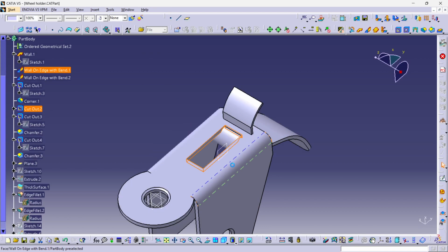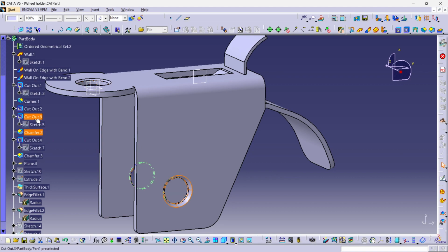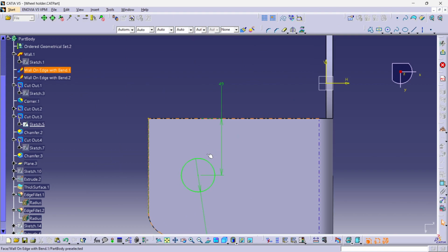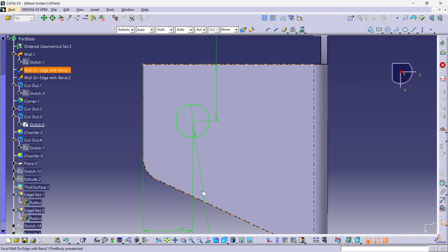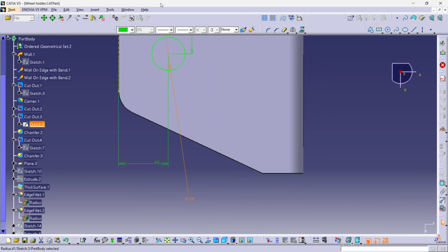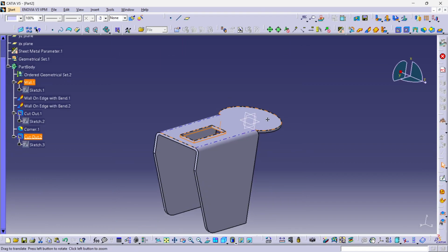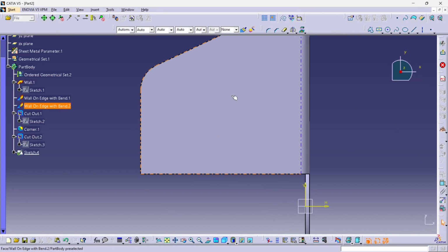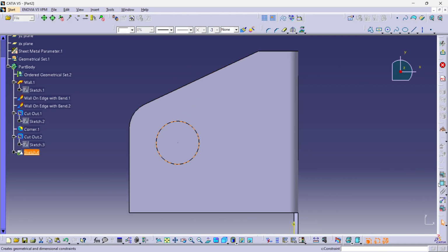And going back here, now let's go for this holes. Okay. This is 49 from this side, 43 from this side, and the diameter is 29. So just select this plane, the middle plane, right? Go for sketch. In here, select a circle. Diameter is 29.